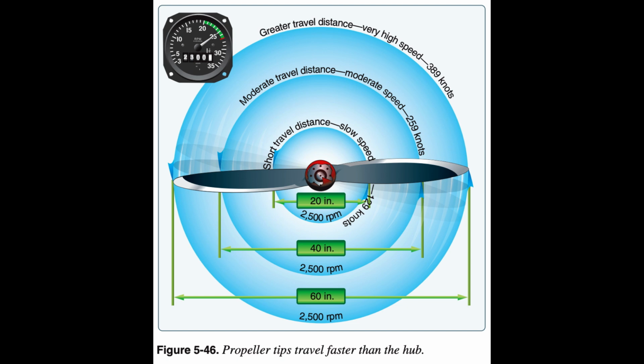During takeoff, when maximum power and thrust are required, the constant speed propeller is at a low propeller blade angle or pitch. The low blade angle keeps the AOA small and efficient with respect to the relative wind. At the same time, it allows the propeller to handle a smaller mass of air per revolution. This light load allows the engine to turn at high RPM and to convert the maximum amount of fuel into heat energy in a given time. The high RPM also creates maximum thrust because, although the mass of air handled per revolution is small, the RPM and slipstream velocity are high, and with the low aircraft speed, there is maximum thrust.